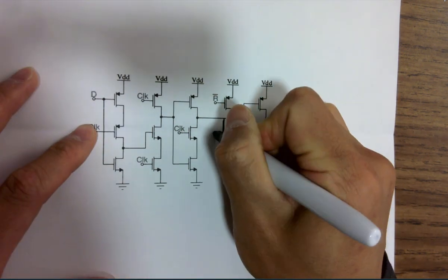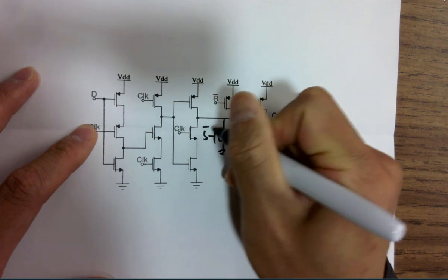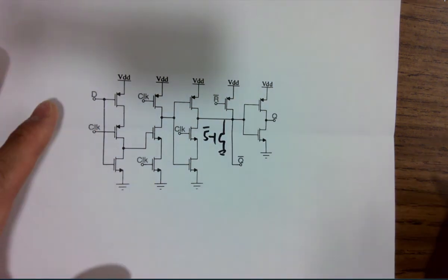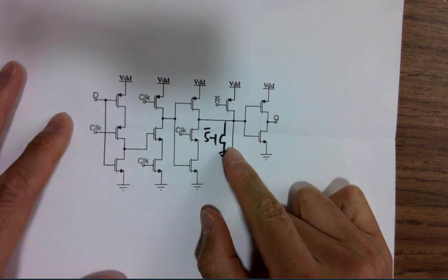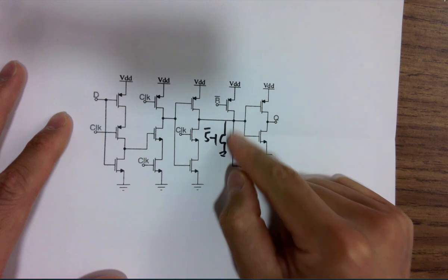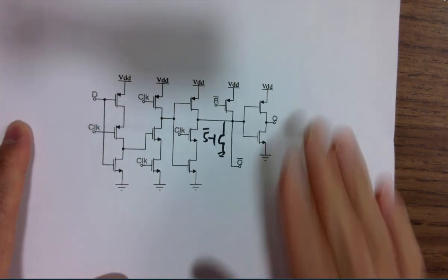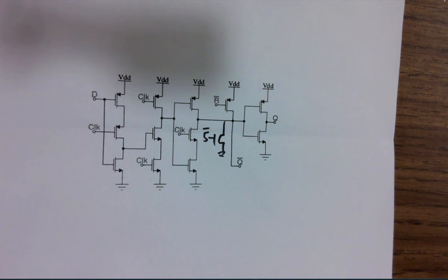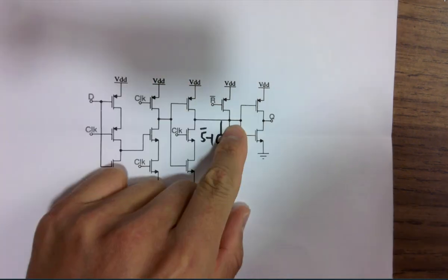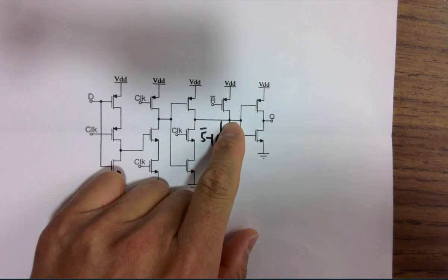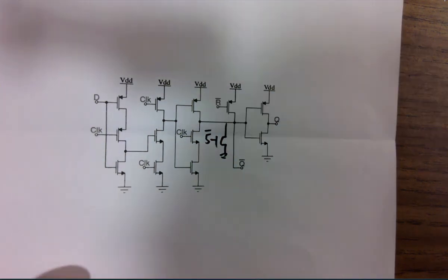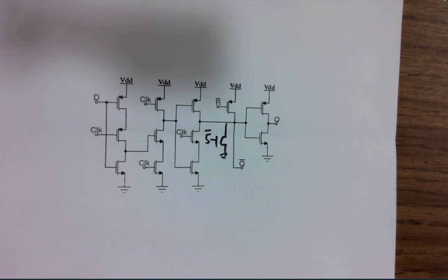Right? So that's set. But you are not setting and resetting at the same time. Why? But if you do it, what's going to happen? Setting and resetting, you want to turn on the PMOS and NMOS at the same time? Short to ground. You are shorting the VDD to ground. It's drawing a lot of current from VDD to ground. It's not doing anything actually. It's competing. So if you turn both off, doesn't matter. This node is just this node. It's just staying there, doing whatever the D flip-flop is doing. And also another quick note here, okay?